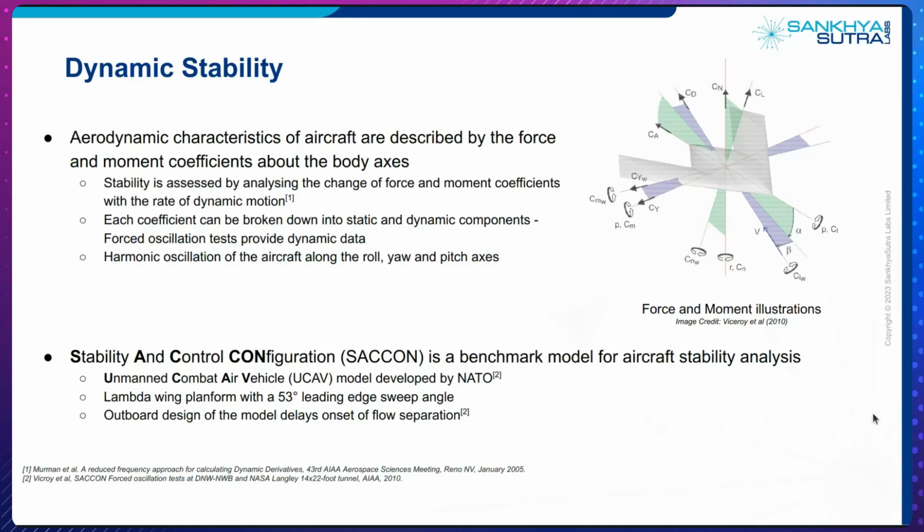So in our case, we'll be using the roll as our dynamic motion. And each of these force coefficients or moment coefficients can be broken down into the static and dynamic components. And the forced oscillation is what lets us test and obtain this dynamic data.